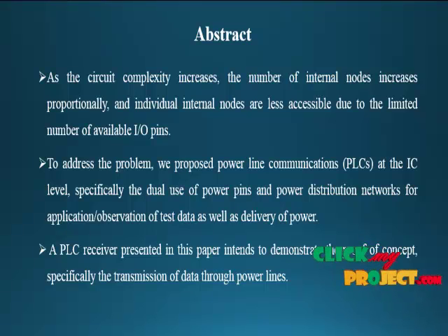With each new generation of deep submicrometer VLSI technologies, testing, debugging and diagnosis of VLSI circuits become more difficult and expensive. In addition to higher circuit complexity for deep submicrometer technology, larger process variations, greater interconnection delays relative to transistor switching time, and larger leakage current also contribute to make the testing more challenging.